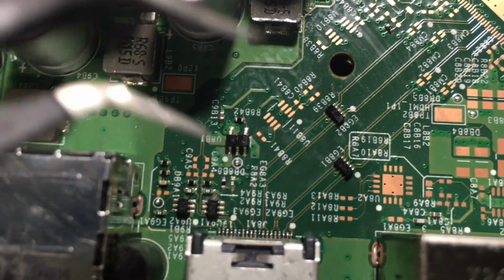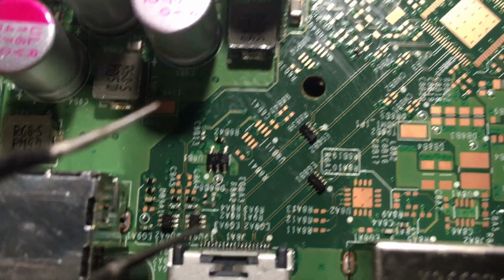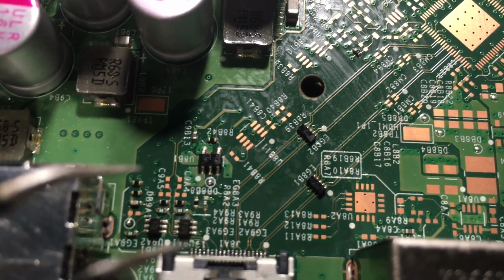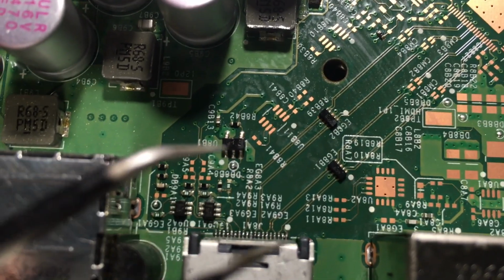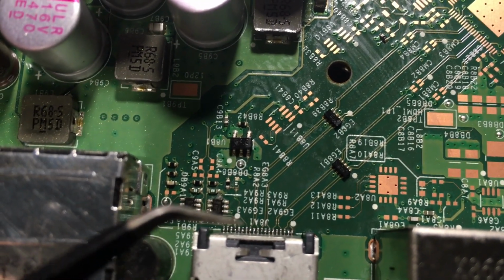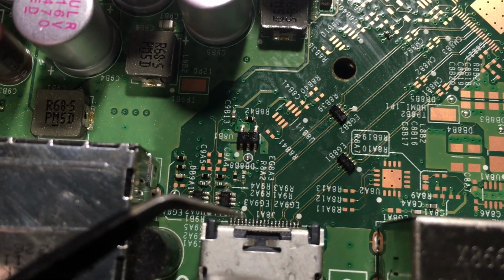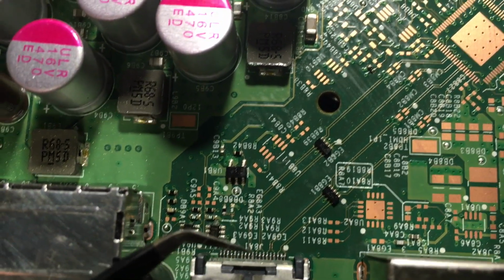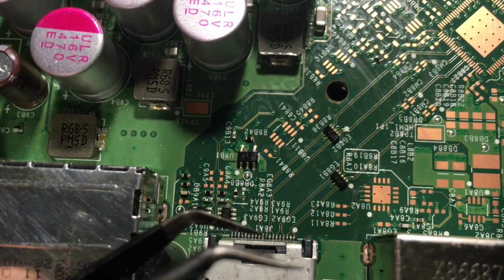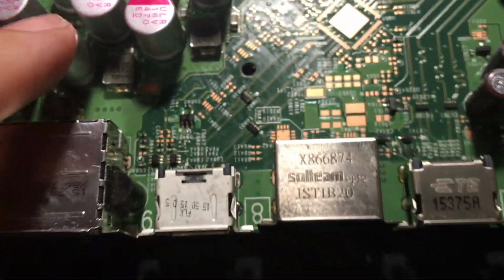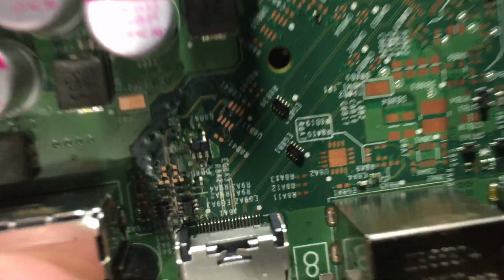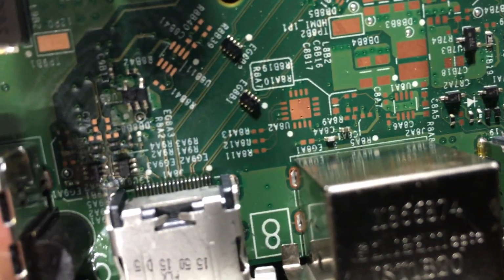I have these tiny tweezers, and you check each connection. Basically, you run the soldering iron across all 19 connections there. Then I would go through and test each individual connection and move it a little bit to see if it would move. If it did, I'd go back, put the tiniest amount of solder on the end of my soldering iron, and solder it down again. It took quite a few passes to get each connection soldered down properly. And again, I didn't bridge any of these, so I didn't have to go back and do things more than once. Sorry, I'm shaking a bit. I haven't had enough coffee today.